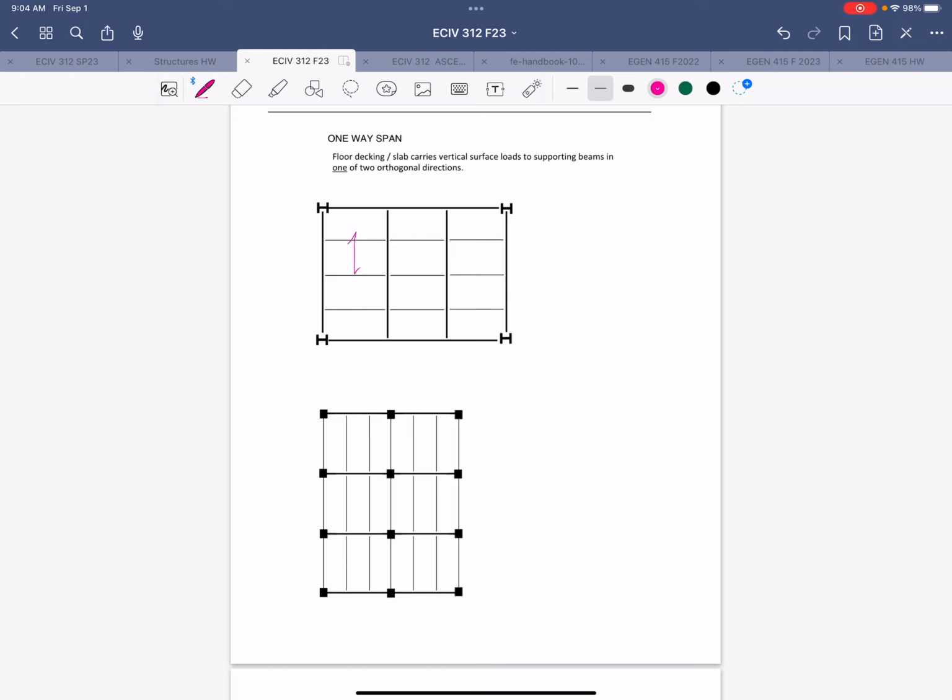And so the hierarchy would be the surface to the cross beam, and then they would go to these secondary girders, all right? Now technically, these girders on the outside would be primary girders, because they're supported by columns. But as far as the hierarchy of the load path is concerned, they're at the same level as these secondary girders, because they directly support those cross beams.